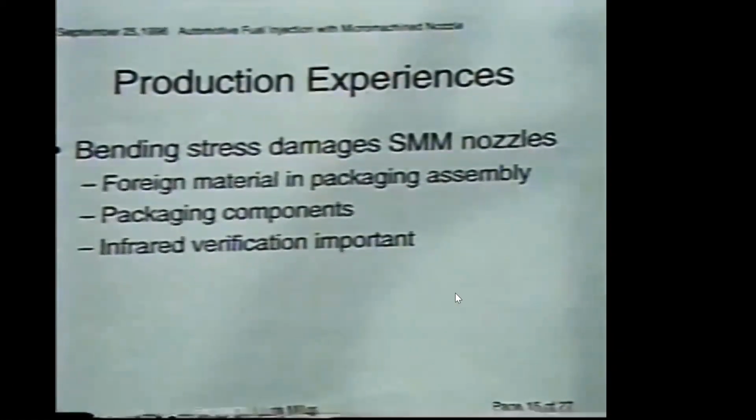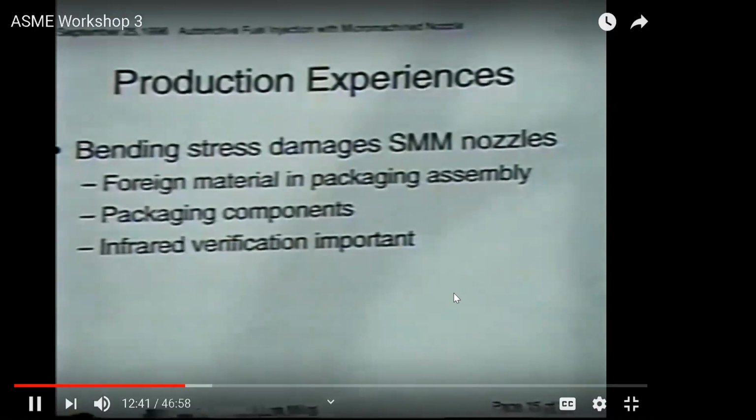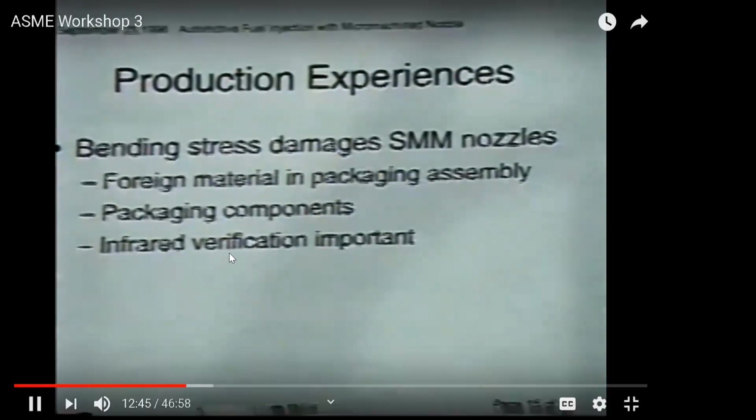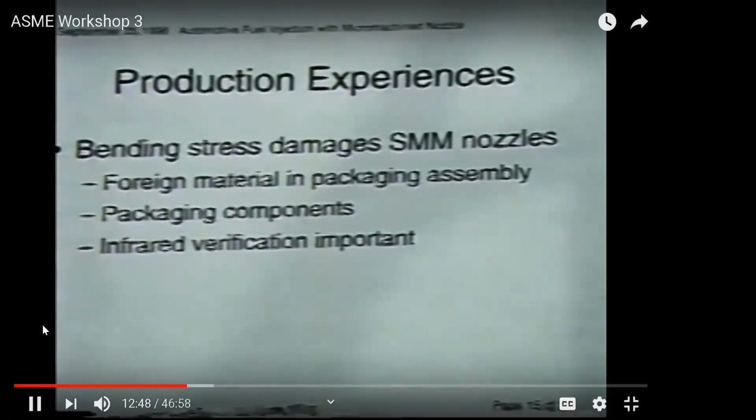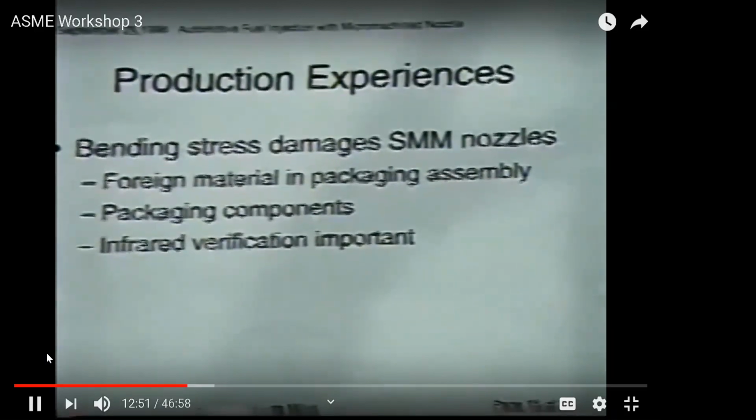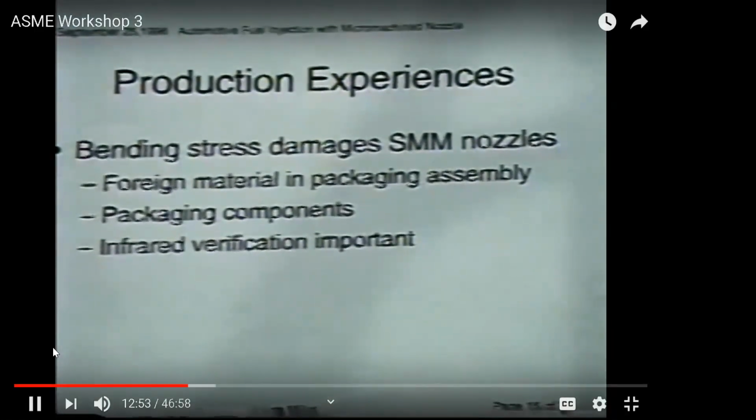Most of the problems dealing with our product dealt with our nozzle in the assembly, and what would happen is that you would end up cracking or breaking these nozzles. They're very easy to detect, but we wanted to get our defect rates down to a low and acceptable minimum number. The biggest contributor to the problem was bending stress on our nozzle, and that was induced by basically two different types of